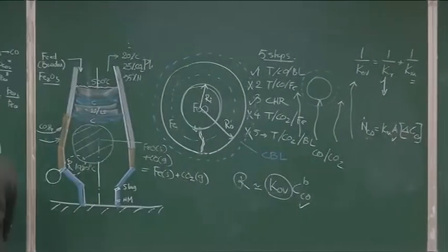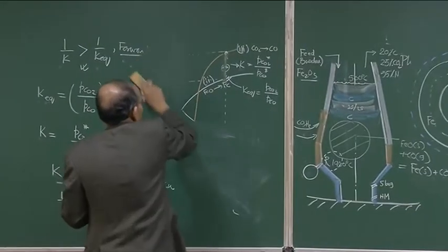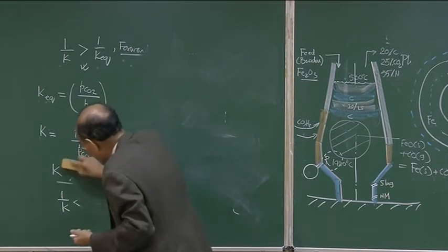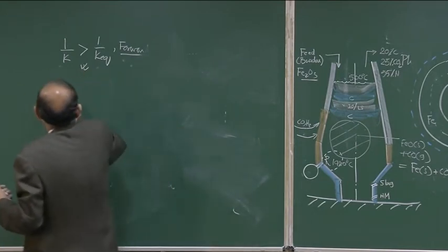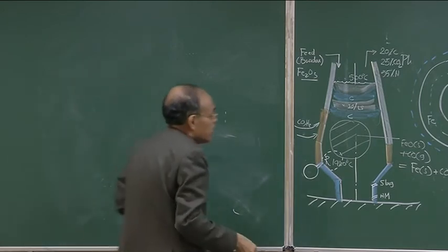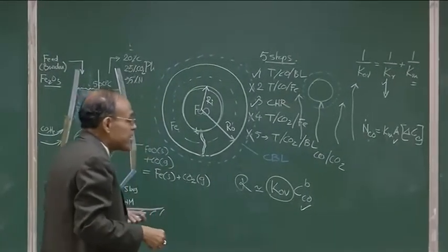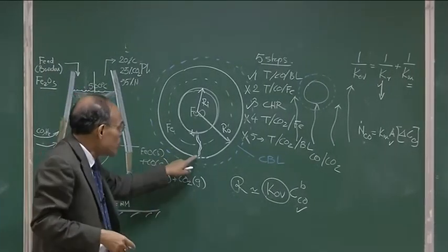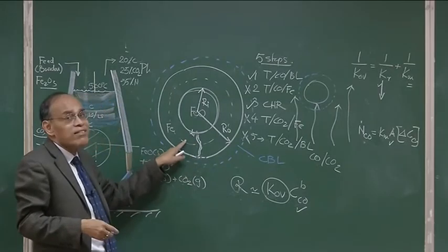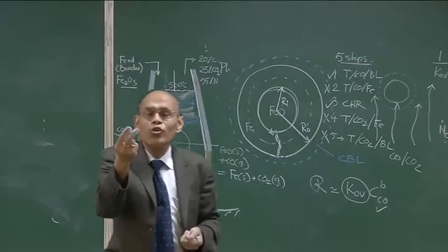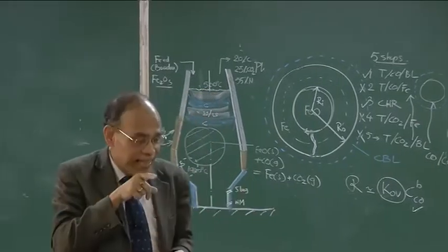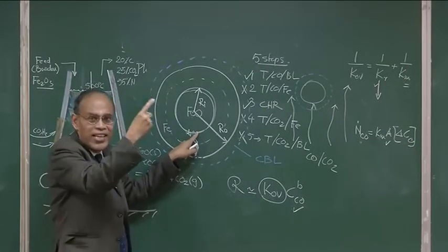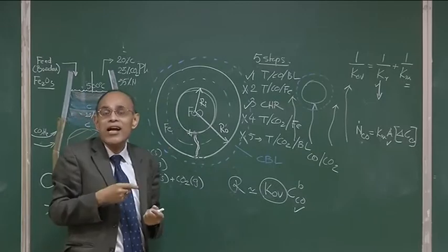So, thermodynamically it is feasible, and kinetics also tells us how we can derive an expression for the rate and understand what the factors are, for example diffusion. That is the reason why we want the pellets not to be too dense. If it is dense, the gas will find it difficult, because the reacting interface is receding as a function of time, going inside and inside, and the path of diffusion is increasing as a function of time.